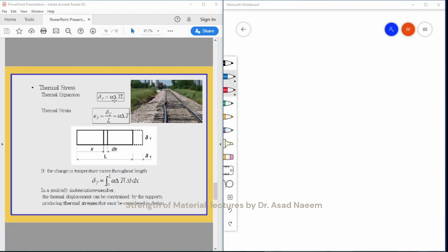So this is called the thermal expansion, and its unit is basically strain per degree centigrade. I mean we take a certain strain per 1 degree temperature change. So we have this temperature change, and this is into length. So the thermal expansion, I mean the delta due to the temperature change, will be the thermal expansion coefficient multiplied by the delta T change into its length, okay. If there is a body which we heat, then it will have a delta change due to the temperature.